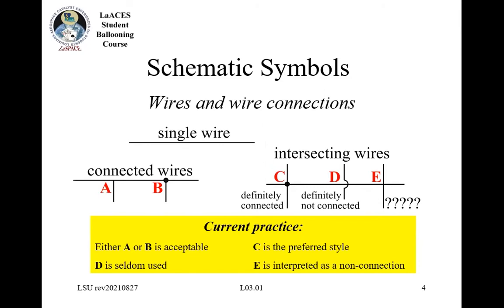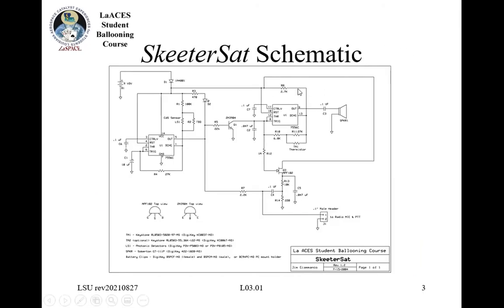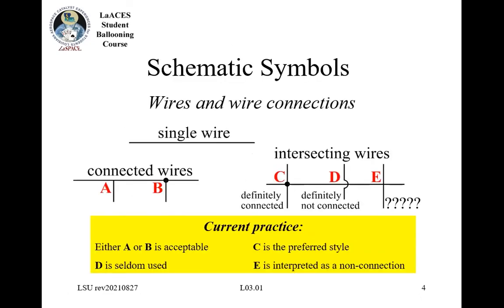All right, so let's just start. First off, you saw a lot of lines here, and these are all wires, literally physical connections touching the components, those different devices. Whenever you have two wires intersecting, that can mean connected wires. It's kind of odd here. This tells me for sure that B is intersecting this top wire, but to me it's a little unclear on A, but this wire does end at this wire, so that's typically connected.